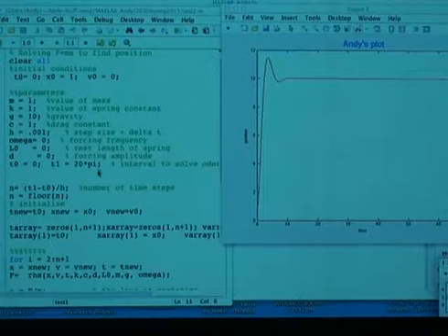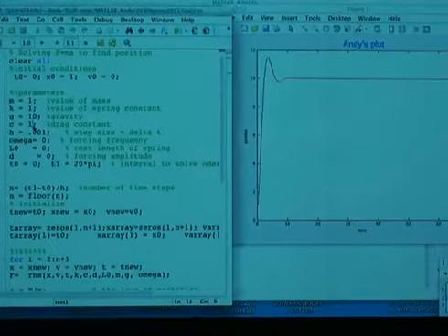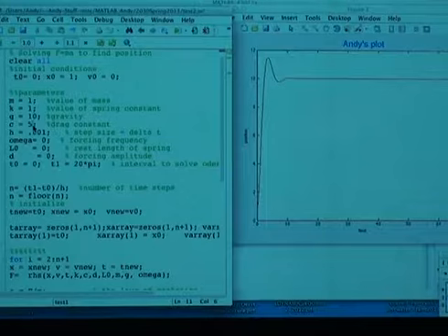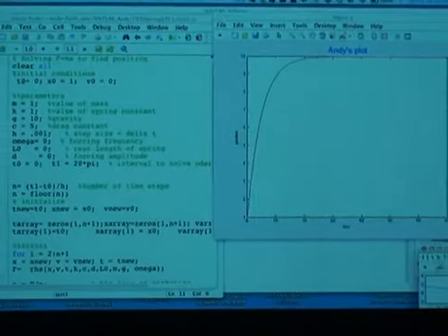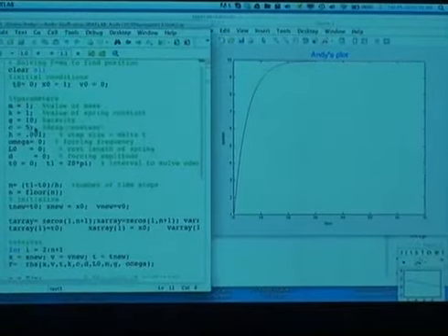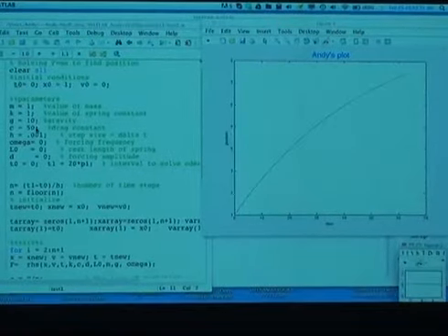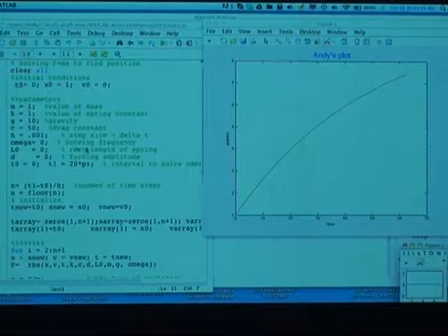There's a keyboard, see, quite damped. I can put in even a bigger damping, like 5, and then it doesn't even decay as fast. And I can put in a bigger damping, like 50, and then it barely decays at all. So what happens if you have huge damping? It just locks the system up, and it takes a long time to decay.